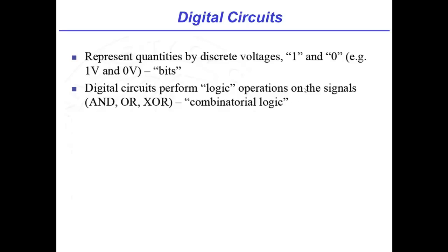That's right. To give you a specific example of that, let's say we had that 5-volt system that you talked about, and its 0 is defined as 0 volts, and its 1 is defined at 5 volts. The system might just decide that anything above 2.5 is called a 1, and anything below 2.5 is called a 0. So any wiggling that happens around 5 or around 0, you get to ignore. That also makes these systems really, really robust, so small changes in the voltage don't mess things up. Oh, I see. And so that's really what we meant by, in the analog slide before, that the analog circuits were a little more finicky. That's correct. And by the way, that's also why it's possible to build digital systems with billions of transistors and have them work, because we're just more robust overall.